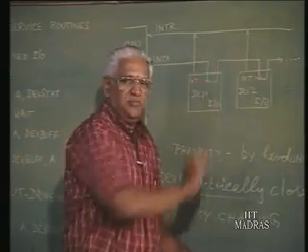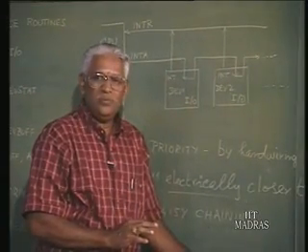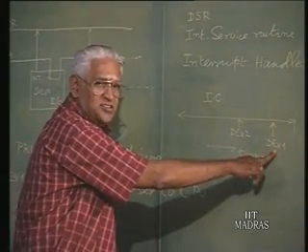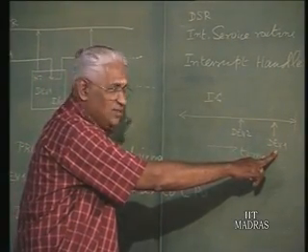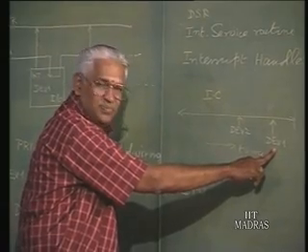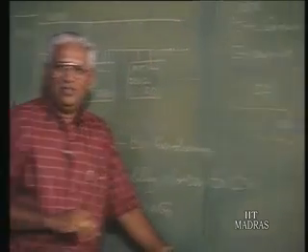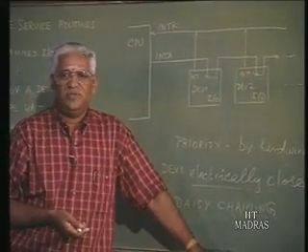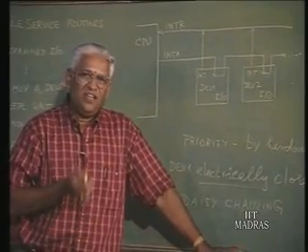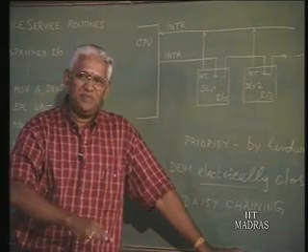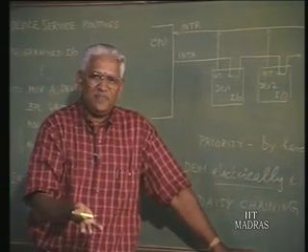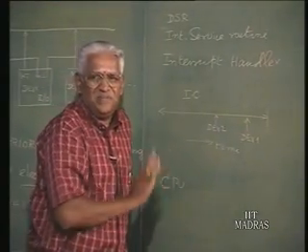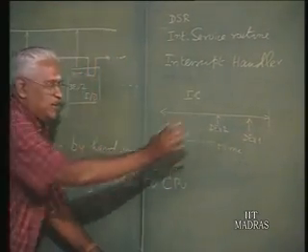Now, this interrupt input will be there. CPU, after it finishes one instruction cycle for device 1 service, will be interrupted because device 2 has flagged the interrupt input. Now, what happens? The device 1 service has been interrupted; mainly it is just a program. As long as the instruction cycle is completed, it can be interrupted.